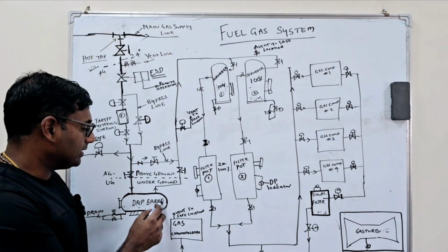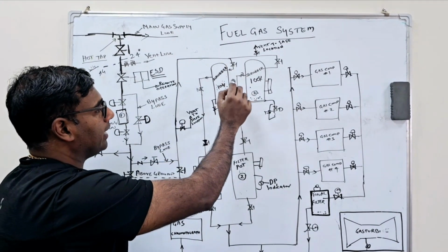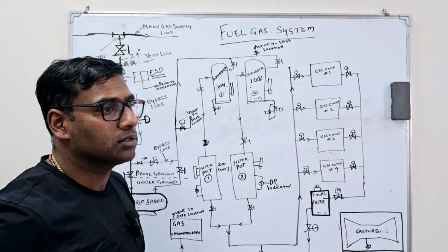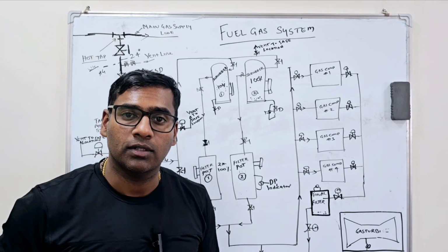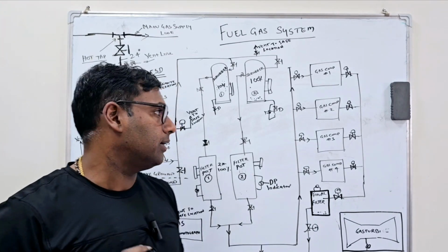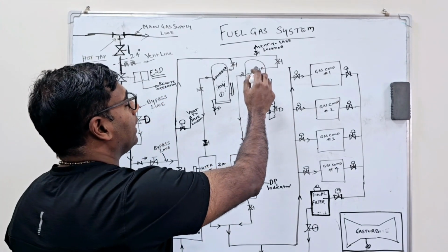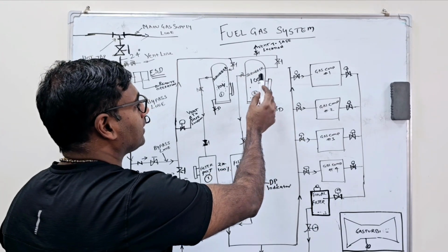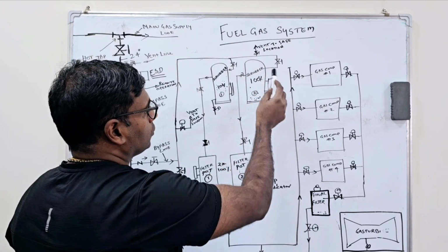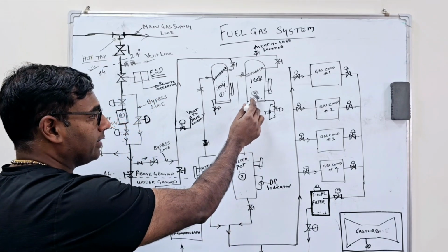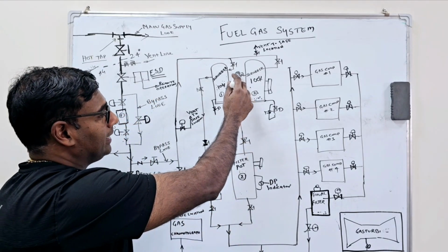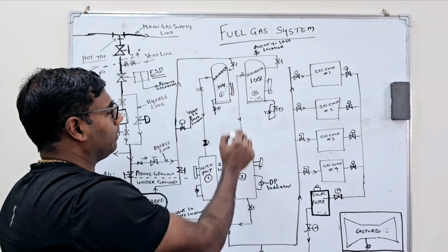As soon as the gas exits the drip barrel, it goes to equipment called scrubbers. Scrubbers are mechanical separators which take the heavy particles out of the gas by the principle of vertical cyclonic separation. As soon as the separation is done, all the heavier particles accumulate at the bottom, and the light gas goes out of the scrubber.